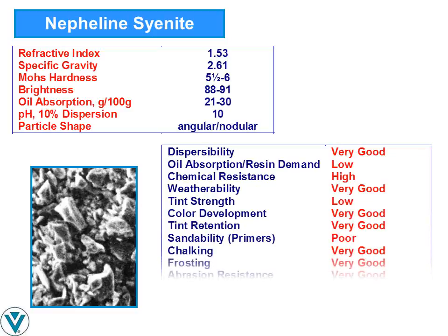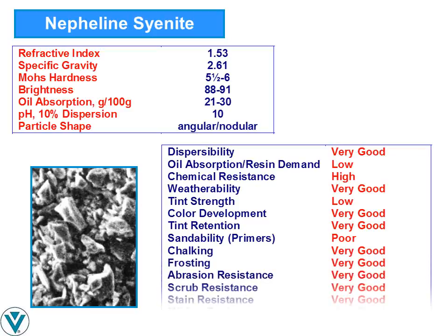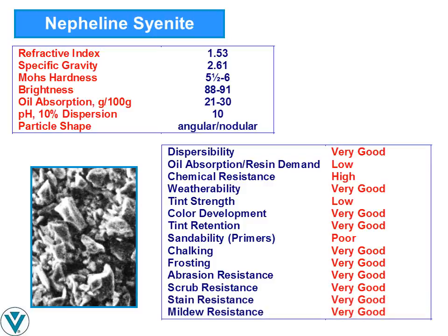Dry film durability confers crack resistance and, in combination with relatively high filler hardness, provides high abrasion, scrub, and burnish resistance. Shape and particle size distribution also promote flatting and uniform low-angle sheen. Nepheline syenite has very low tint strength, contributing minimal color at high loadings. Film reinforcement, chemical stability, and resistance to chalking promote high tint and gloss retention on prolonged exterior exposure. The low refractive index of nepheline syenite allows for higher loadings in clear and semi-transparent coatings and stains.